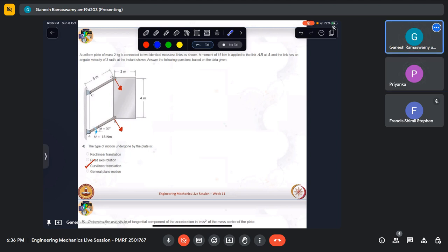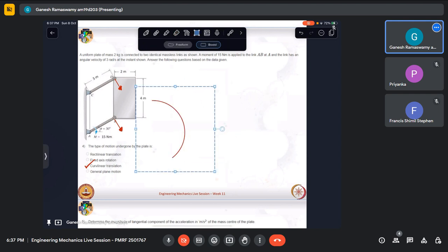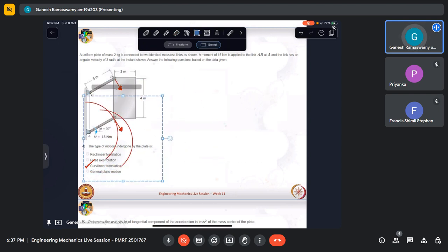Yes. Naturally. So if the lengths were different, let us say that this arm was connected like that. In such a case, the two velocities are not parallel. We can clearly see. In which case, it'll be having rotation also. So by virtue of this being equal, the path undergone by this would be a circle. Let us say that this is the circle, a circle like that. Similarly, this will also undergo a circular path like that. In which case, the entire system is undergoing a circular motion.